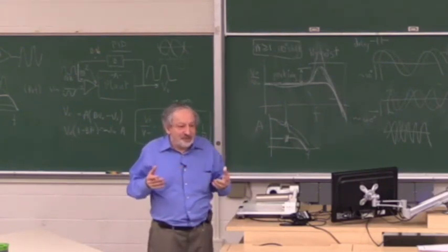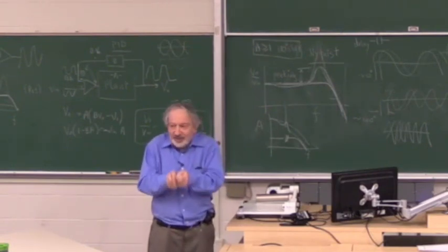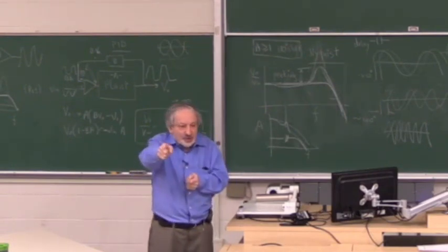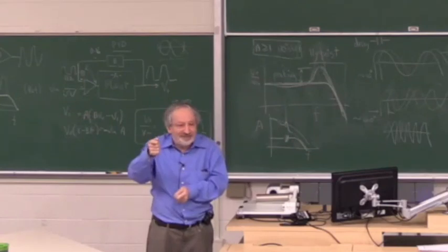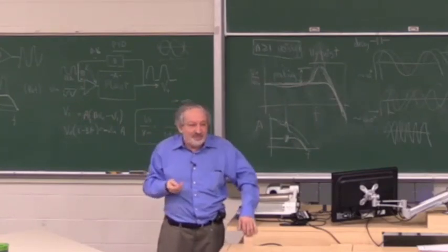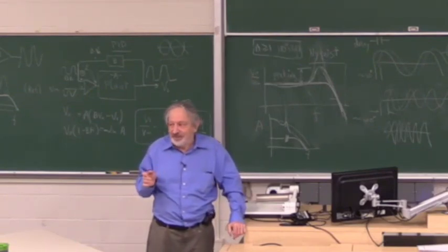That's the phase shift. So when things resonate, if you take a cantilever and you drive it by hand and you measure the position, near resonance the tip position doesn't follow your hand position. It could actually be in antiphase, because that implies a huge phase shift. It means you can never stabilize it. Okay. Is that clear?